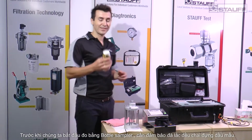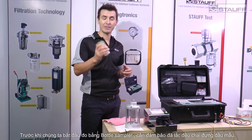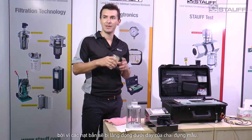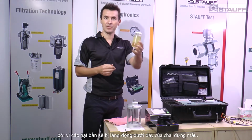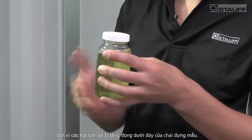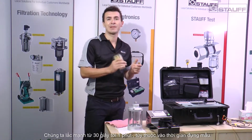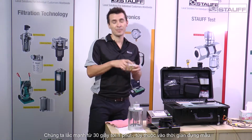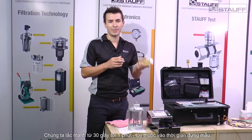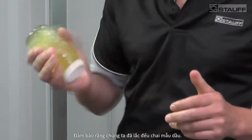Before you take the test, make sure you shake the bottle to evenly distribute particles, as if the oil sample has been sitting for a long time, all the heavy particles may settle at the bottom of the bottle. So do that for approximately 30 seconds to 1 minute, depending on how long the bottle's been sitting there. So just make sure you shake it.